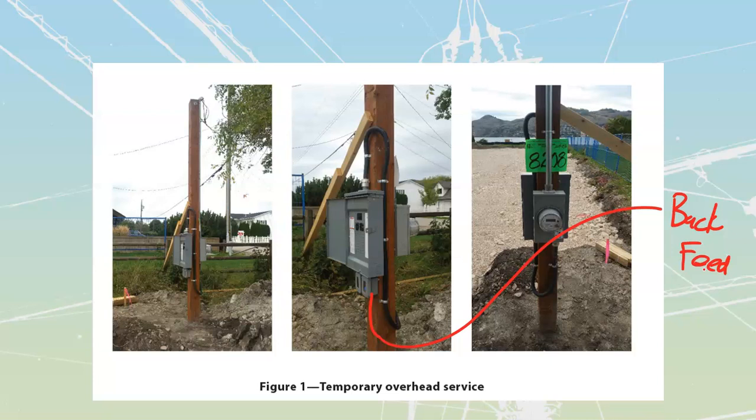It's actually highly illegal, because everybody that's inside of the house should be working off the temporary power, and if for whatever reason hydro came and connected to the main power while you still have this backfeed inside there, you're going to end up with a line-to-line fault that's going to be there when they go to close in. So we're just not allowed to do that.